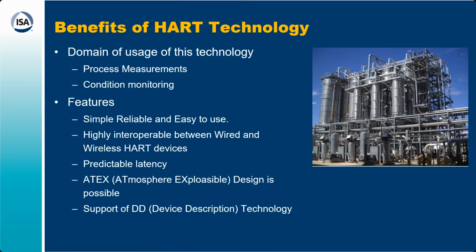So basically, this technology, as we discussed, is used in process measurement and condition monitoring. Plus, it is simple and reliable to use. It is highly interoperable between wired and wireless HART devices. Wireless HART technology has a predictable latency too, because it works on the advanced TDMA technology. We'll talk about that. Plus, ATEX design is possible because you can use this technology in explosion-proof areas. It has support of device description and FDI technology. So many benefits are available so that the customer can use this without having any glitches in their existing plant network.